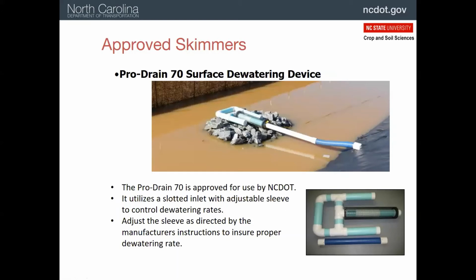And here I want to show you also the standing pool. So we've got that pipe going through the dam at a foot above the bottom of the basin. So we have about a foot of standing water here. Why is that? Well, there's a lot of reasons. One is that's the dirtiest water. So you picture we fill up the basin, sediment's constantly settling. So at the bottom, that's the dirtiest water. And so in this case, we're going to leave the dirtiest water in the basin, let it settle some more before the next storm.